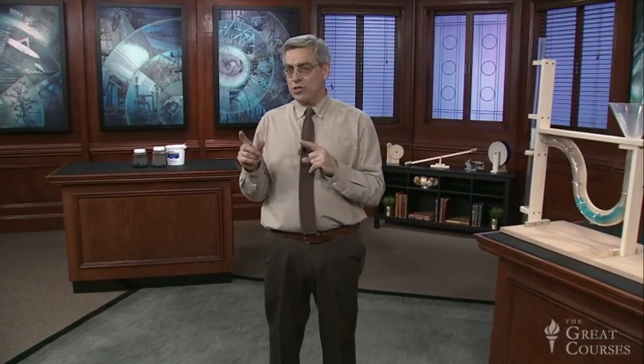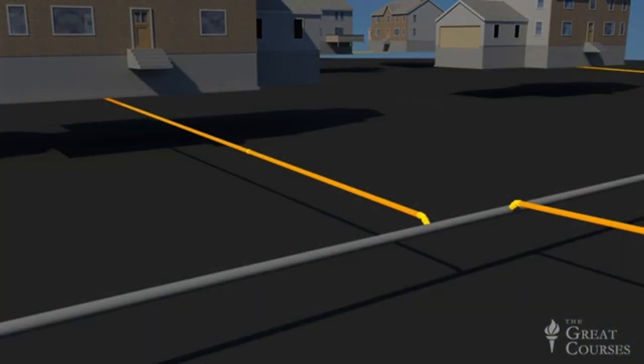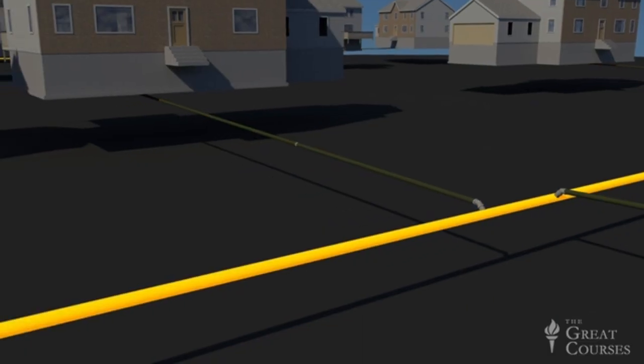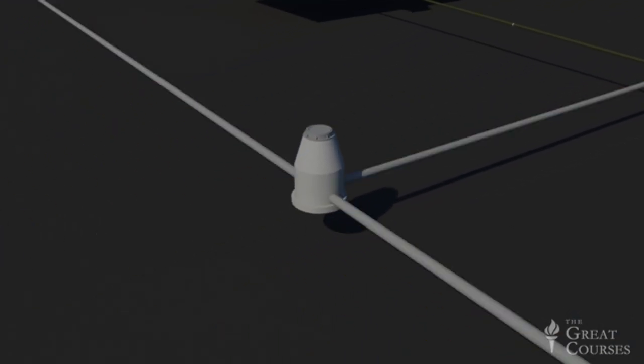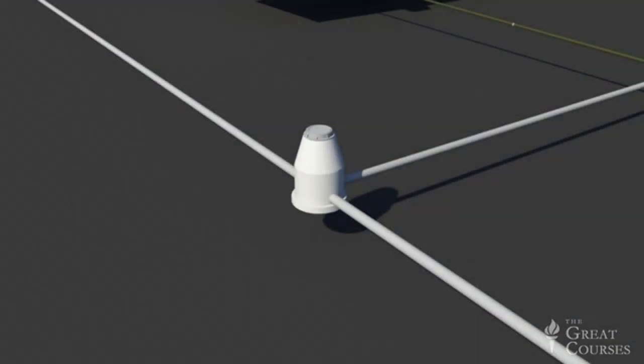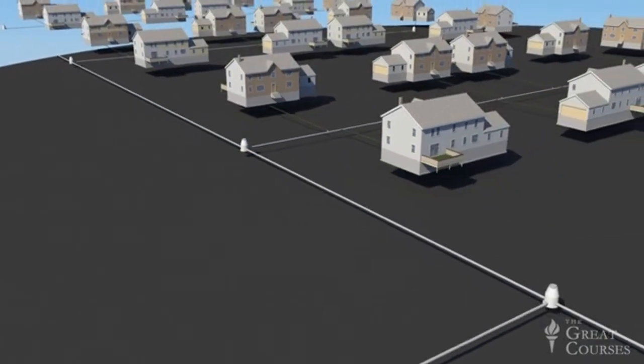As wastewater flows from the soil stack, it enters either a municipal sanitary sewer system or an on-site septic system. The sanitary sewer begins with a lateral. That's the underground pipe that runs from your soil stack to the street, where it connects to a larger pipe called a branch. Branches feed into progressively larger pipes, typically called trunks and interceptors, in a tree-like topology very similar to the one we saw in storm drainage systems.